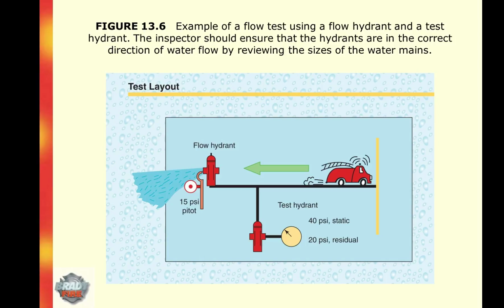This records the remaining pressure on the system and should drop the static pressure by at least 25% or 15 psi to validate the flow data. If the flow has not decreased the static pressure by 25% or 15 psi, open an additional fire hydrant outlet until you get a sufficient drop in pressure.